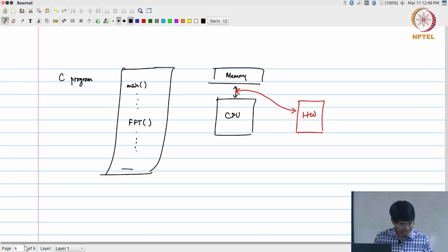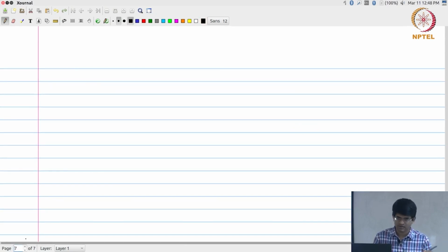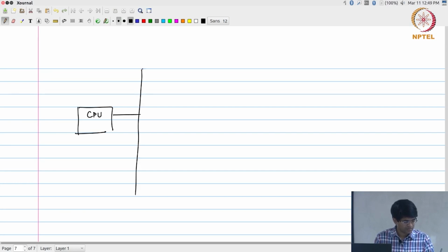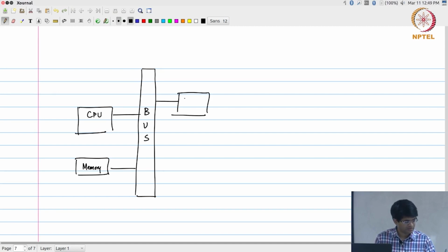And the way that this is done in practice is that we build up a system that has all of these capabilities, and in order to take care of the talking between modules, right, I have something that we call a bus, and this bus allows me to have my accelerator module attached to it in such a way that when certain instructions are seen by the CPU, they will automatically send information to the accelerator, which will perform whatever work it is supposed to do and give me back results. Okay.